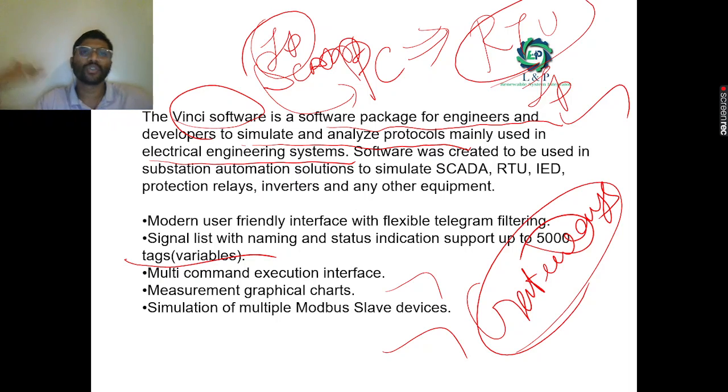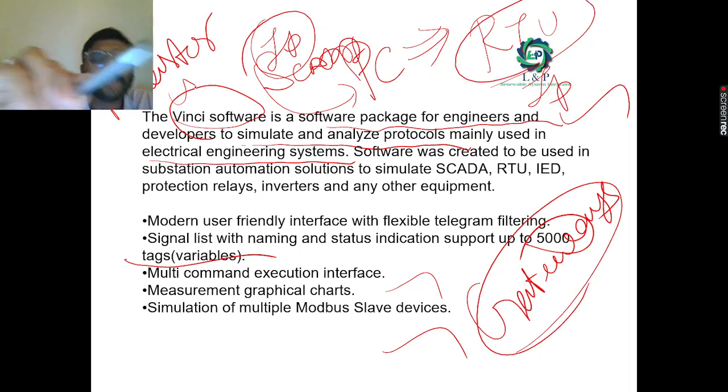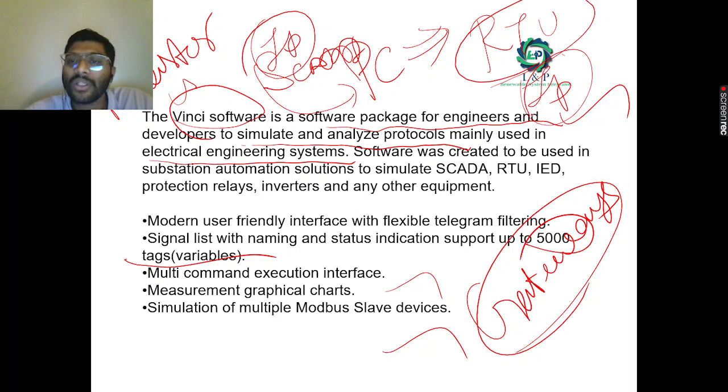If there is an issue with the SCADAs, and you want to cross confirm whether you're sending the correct data through your gateway to the concerned SCADA, then in order to cross confirm it, your PC is going to act as a master. You will make your PC a master and assign the gateway address to your PC. Then you will connect with the different RTUs through the IP address of the concerned RTU, so that you can see all sorts of readings.